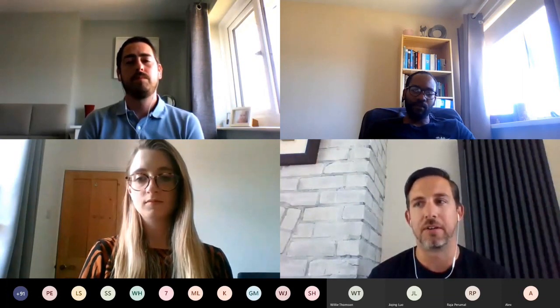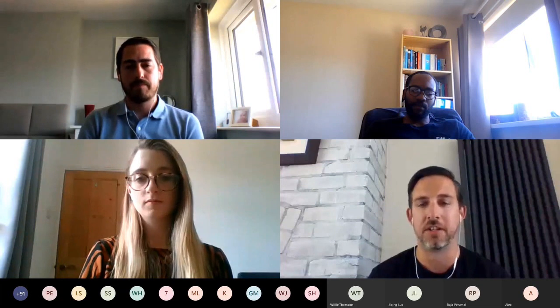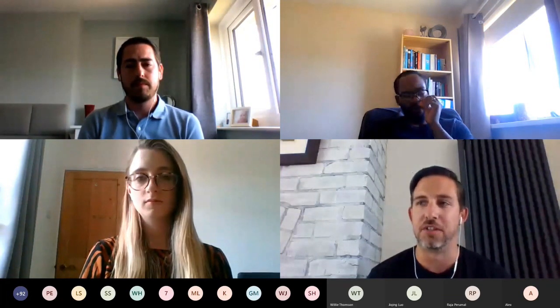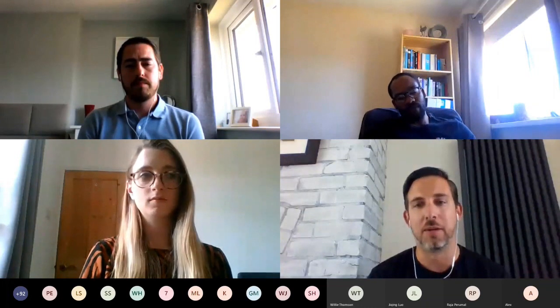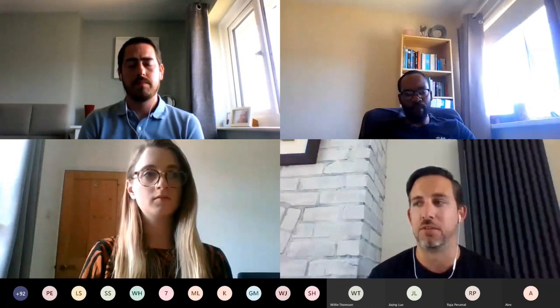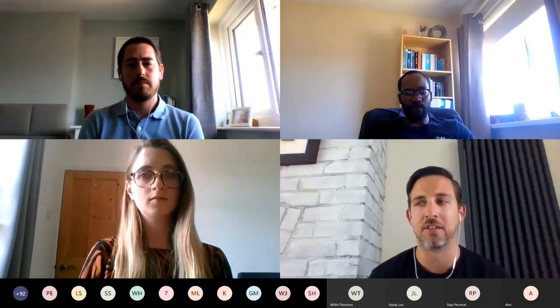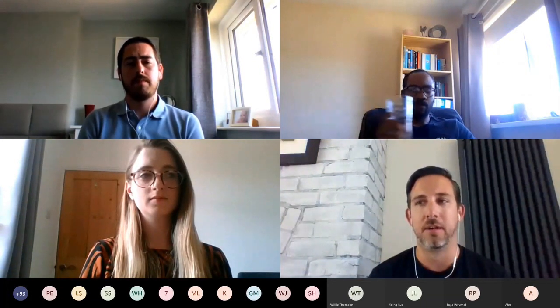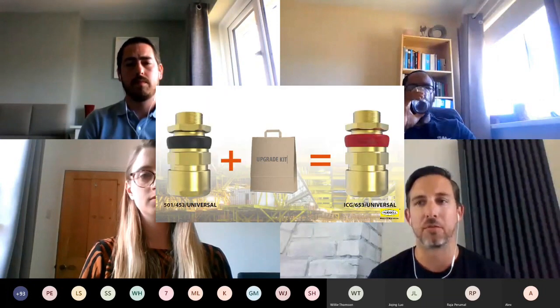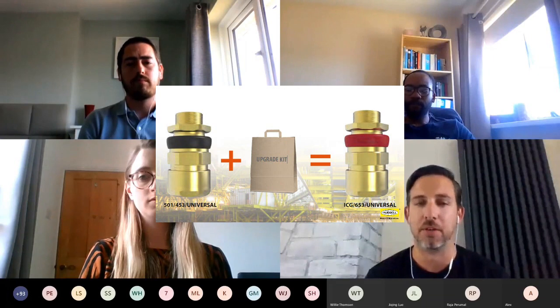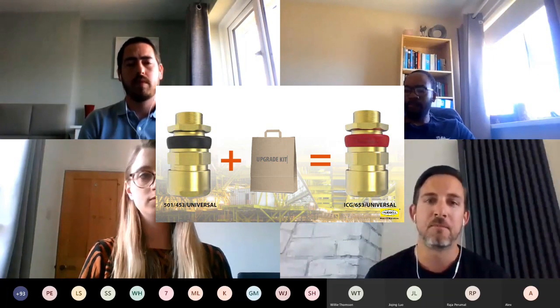Because Hawke have thought about our range in that way, almost like a modular range, it's given us the ability to rationalize components between the different gland types. What that means is we've unlocked the ability to purchase a dual marked universal and ICG gland, and then have the ability to upgrade that from a universal gland to a barrier simply by swapping out components within the gland itself. Absolutely.